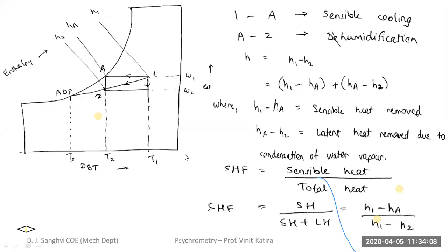And if you have a kitchen wherein there is a lot of cooking and a lot of boiling taking place, naturally the cooking process is going to add a lot of water vapor into the room, and that is going to add to the water vapor content. That means we are adding latent heat into the room, because there is a change of phase happening. The water that is being boiled gets converted to water vapor. So you're adding latent heat, or change of phase of the liquid is happening.